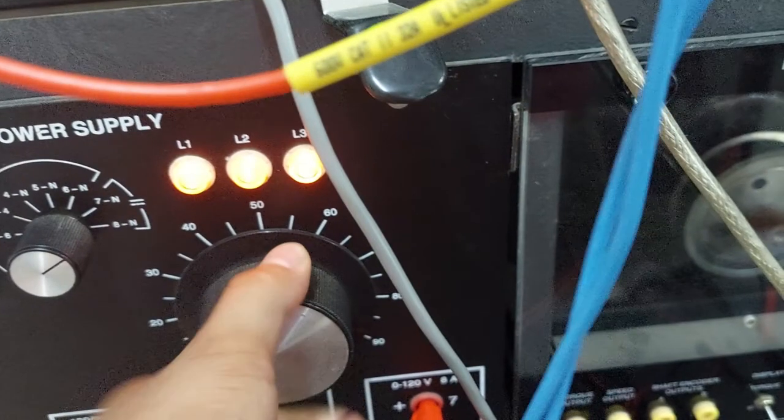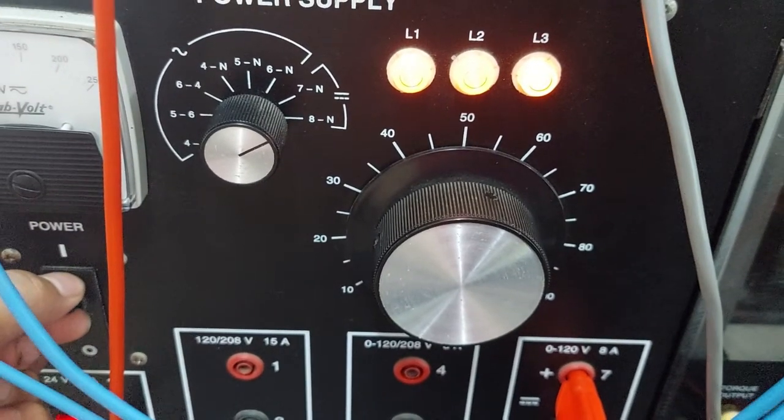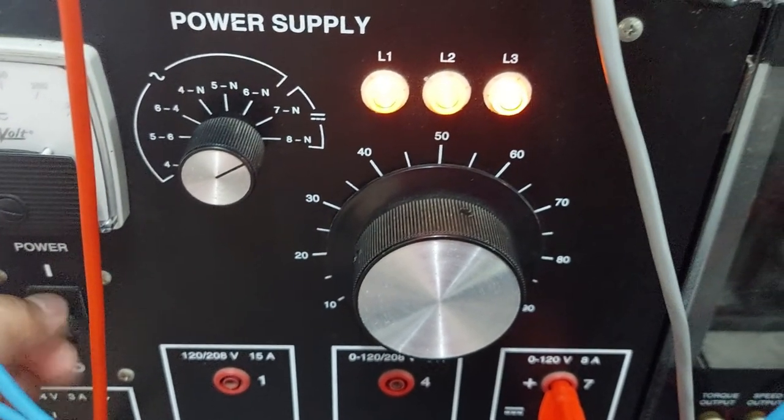In order to verify your calculations from our ammeter and voltmeter, let us read the resistance through our multimeter. So in order to verify the value of the resistance that you have computed from the reading of our meters, let us turn off the power supply in order for us to use our multimeter to read the resistance in the parallel combinations of the resistors.